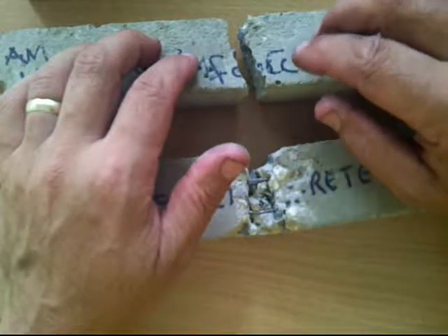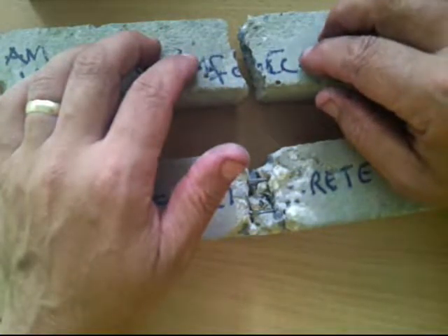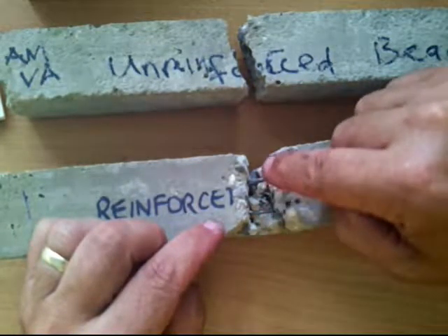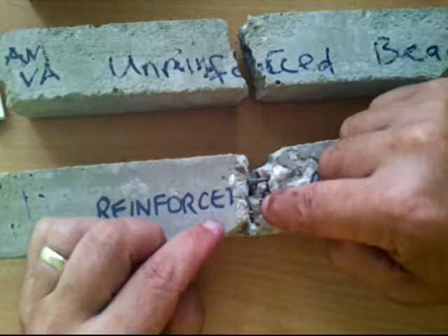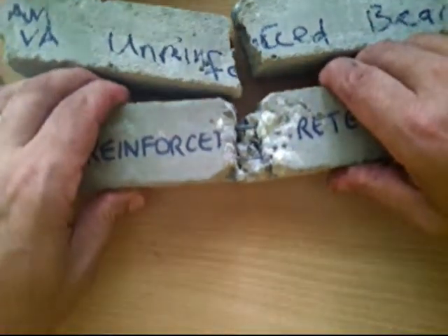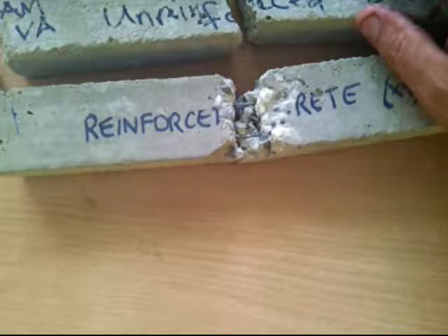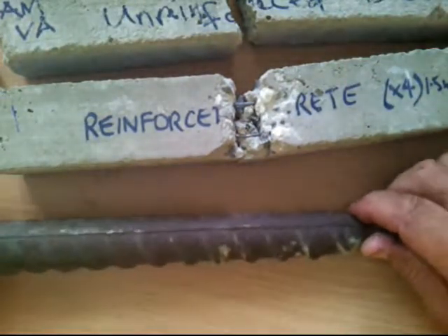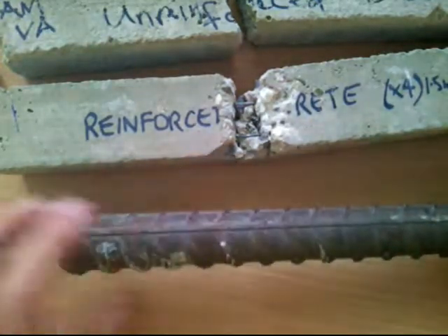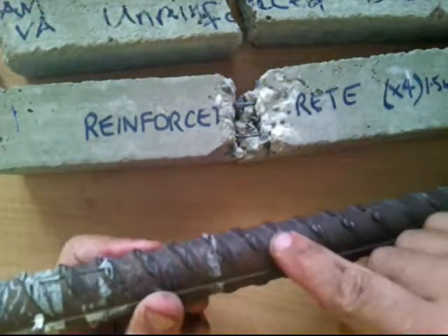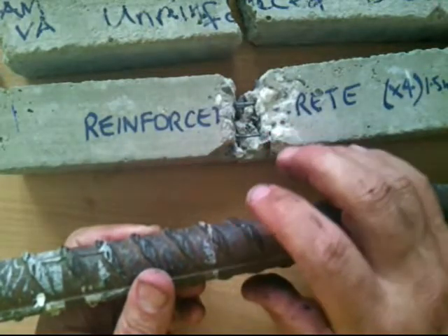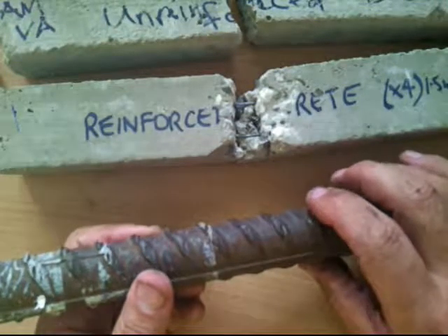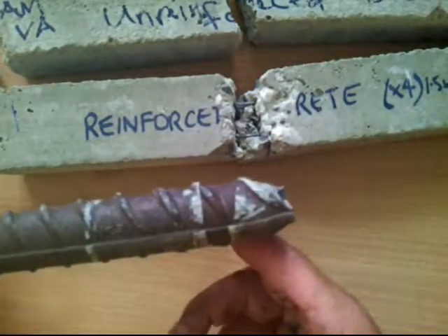So what that says to us is that the properties of concrete, which are hardness and brittleness, have been considerably modified by placing it or mixing it with steel, in this case mild steel, galvanized mild steel wire. But in real life, instead of using galvanized mild steel wire, we would be using a large reinforcing rod, or rebar reinforcing bar like this. It's a fairly hefty one, and you can see it's ribbed on the side here, so that when the concrete sets around it, there's very little chance of this slipping in the concrete when it's under tension.